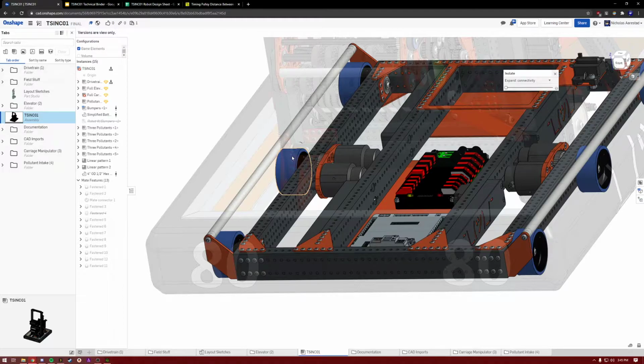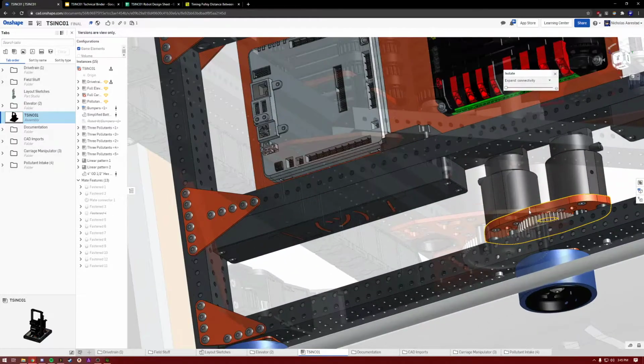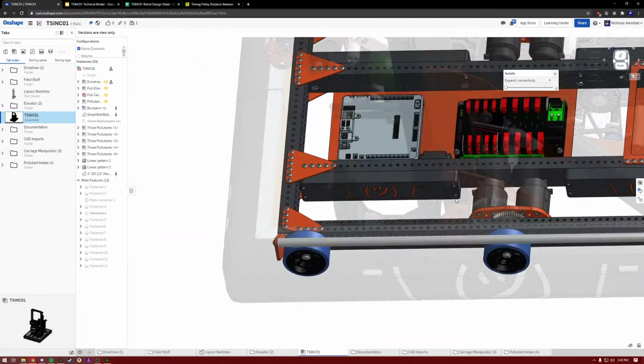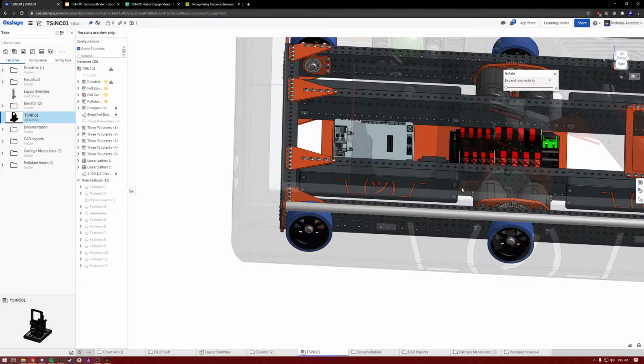3 and 1/4 inch wheels are an acceptable thing in my mind for this game because the field is so flat. You could bump that up to 4 inch wheels. Honestly, that's probably safer. As I was designing this, I considered bumping it up because people are doing partner climbs, and that's probably a good idea because it makes partner climbs bigger. But I just stuck with the 3 and 1/4 inch wheels, partially because I haven't really designed many robots like that. And offseason events are about growth.